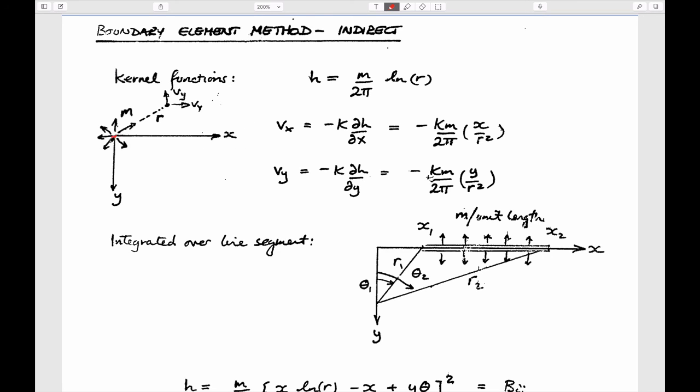And you pump fluid into this little hole so that it goes into the porous medium that's around it. If we did that, it's just like a well. You could imagine going some distance away from this well, which would be some distance x and y. And we could calculate from a solution for this just by solving the continuity equation and using Darcy's law.